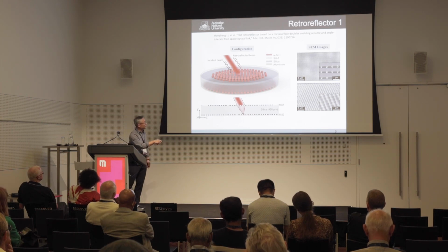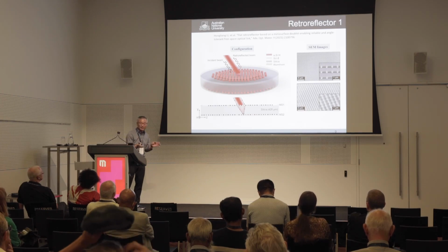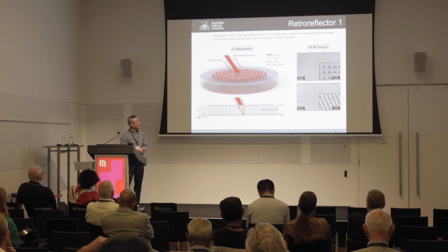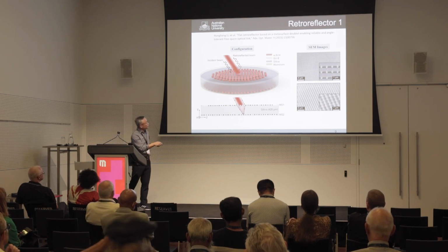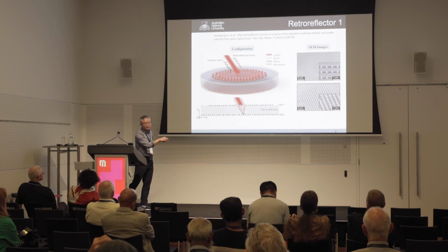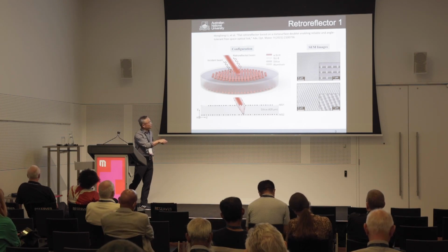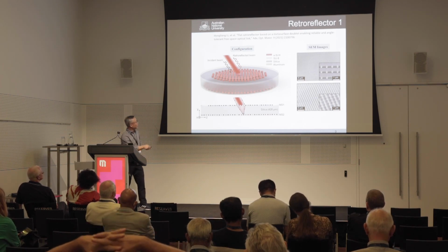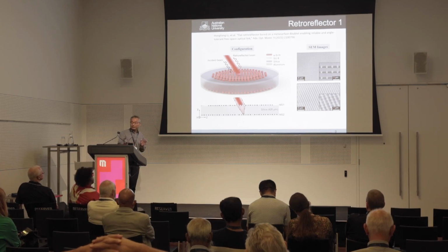The thickness of this silica is very, very important because the focal length of this convex lens and concave lens is exactly matching this thickness. The structure is, the front surface is amorphous silicon again, with a 1 micron tall structure. On the back side it is the same, but with a different phase profile.